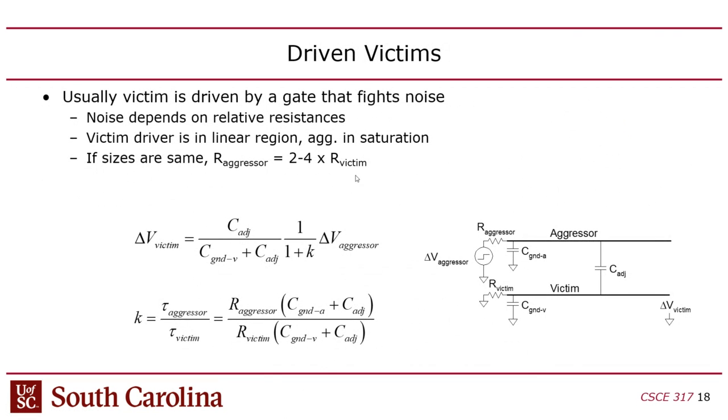The other thing you have to consider is that the amount of noise you're putting on the victim also depends on how powerfully the victim wire is being driven by its driver. So you can also estimate the drive strength on the victim wire. That's where you can adjust this.